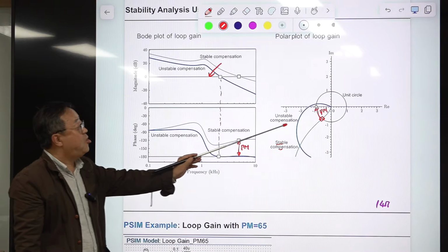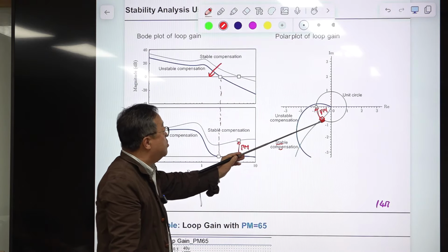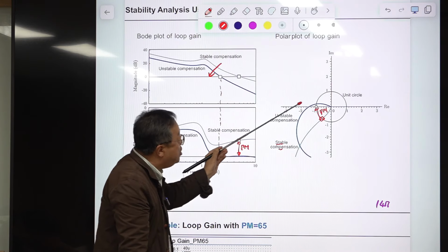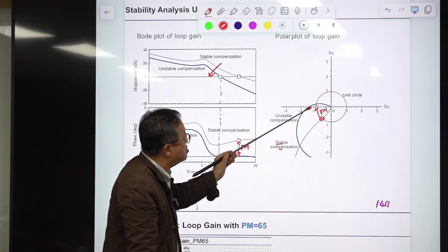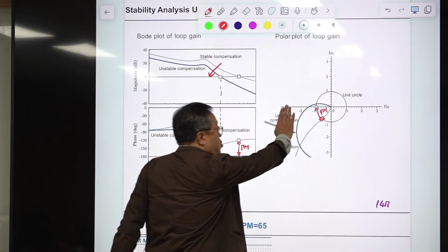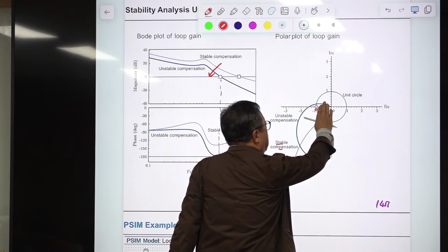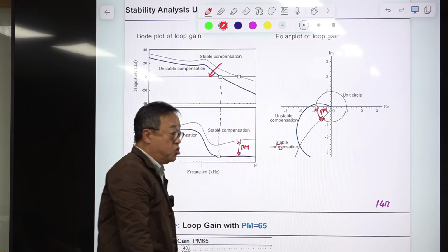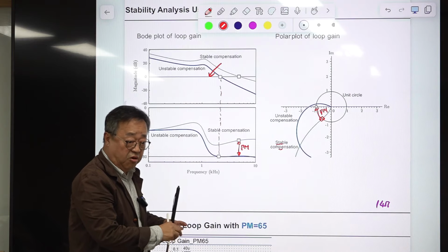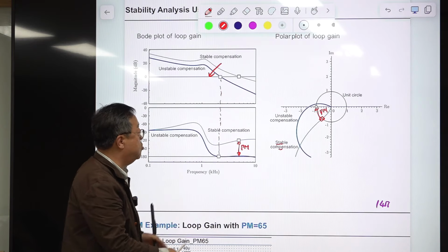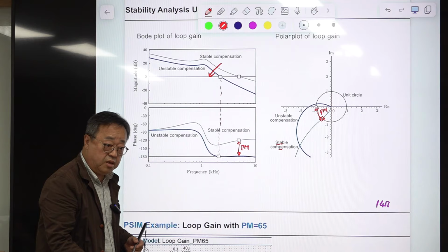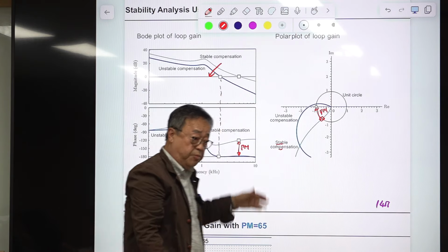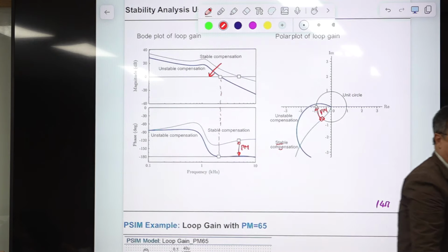So this is sufficiently stable, but with some new design, this loop gain is changed to this one, and this one encircles this point. This is region A, this is point B, region C. It crosses region C, so it is slightly unstable. So it shows growing oscillation. Okay, so you are using this. This is nothing new. This is the typical example of classical control theory.